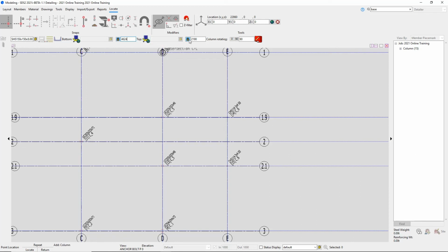as well, and then that elevation is going to be our roof elevation. So we're going to type in 8,371, and then we will keep our 90-degree rotation on that. And now that that's set, we can go ahead and locate it D2.